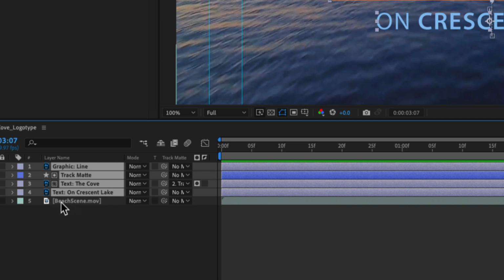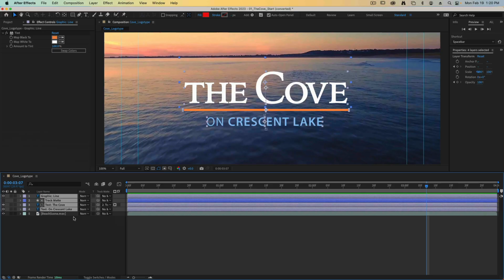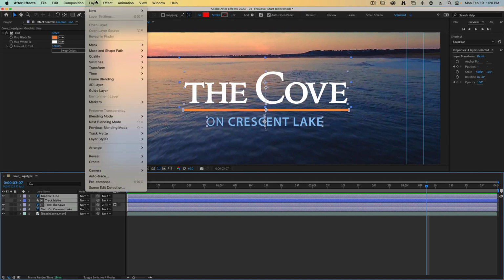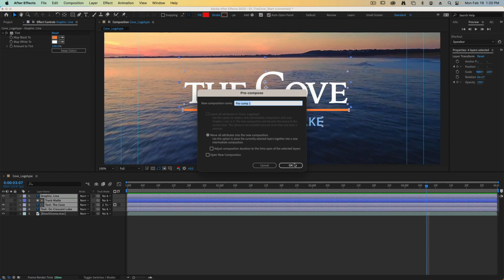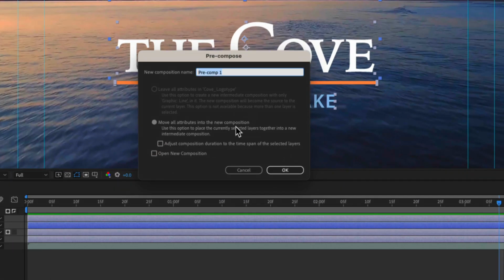Notice that I didn't get the beach scene movie, just all of the ones that have part of the logo to it. Then we can go up to Layer and down to Pre-compose. This is going to ask us to move all of those layers into a new composition. I'm going to call this my graphic and say OK.